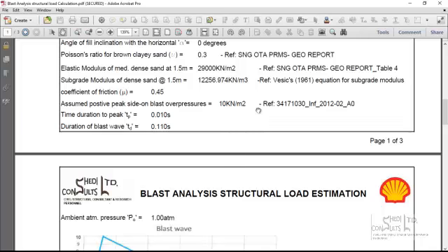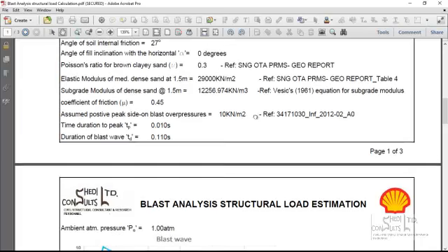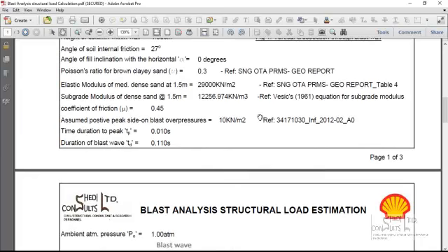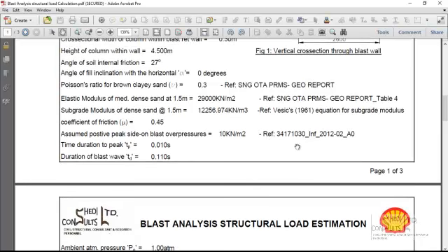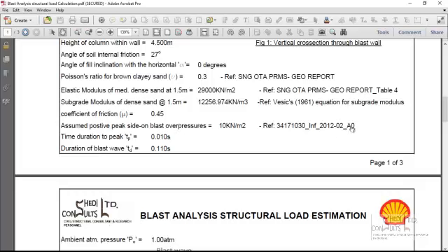I actually told you previously that usually a study is done using a specified process risk tool. You do a qualitative risk assessment to determine the blast zones within the location. You simulate an explosion and calculate the shock pressures, the peak side-on positive phase, the reflected blast pressures, and so on.